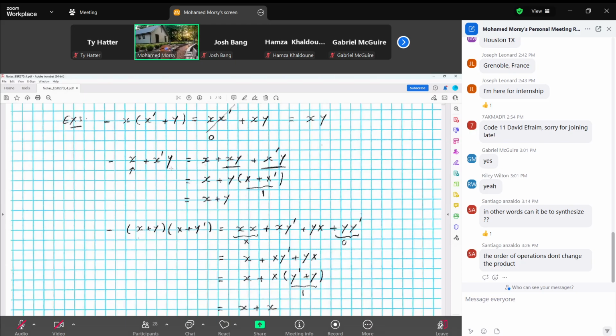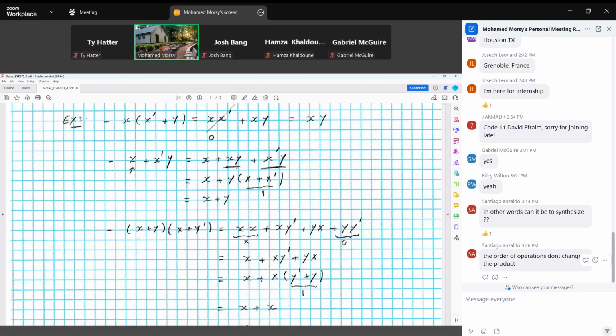Next, X plus X inverted Y. Again, we mentioned this like A plus A inverted B. And we mentioned, ignore X inverted here. Not ignore, of course, just to get the result here. If you ignore the X inverted, it is X plus Y. And we proved it before. We can put X as X plus XY, which is the same as X. The whole thing here is X plus X inverted Y.